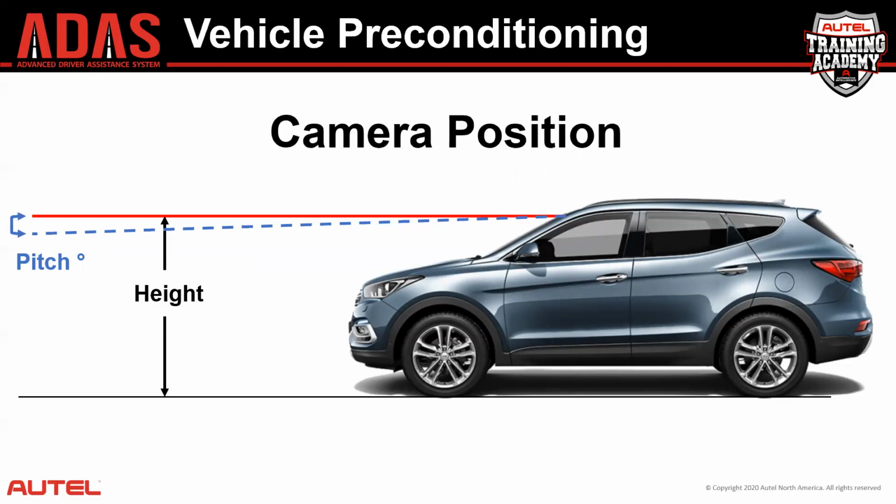So here we have a vehicle. We followed all of the preconditioning instructions to the letter. The gas tank is full, oil and coolant are full, tires are at placard value, there's no load in the vehicle, and our camera height and pitch match, and we perform a calibration. We can feel satisfied that that calibration is accurate. However,